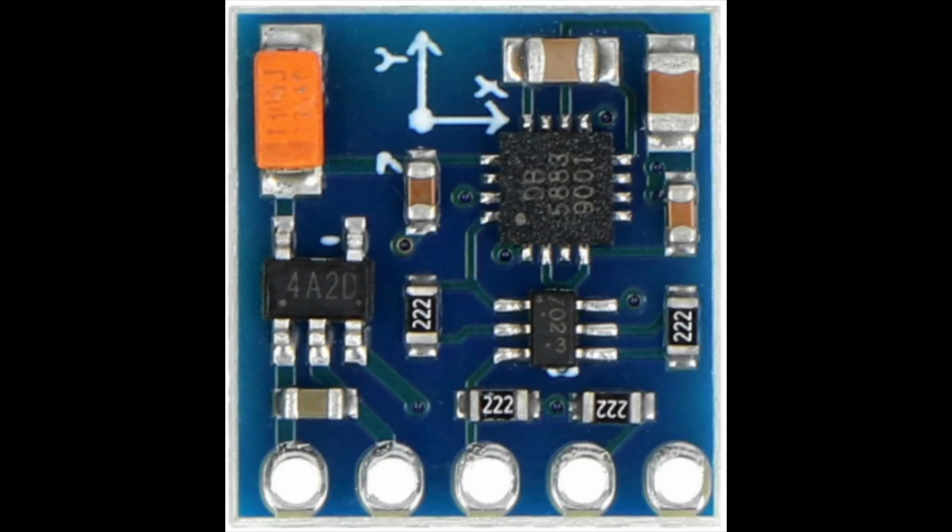Now, in terms of the direction aspect, I use the QMC5883L magnetometer. It calculates the heading by using magnetic field readings from its x and y axes, which measure the horizontal and vertical magnetic field components, respectively.